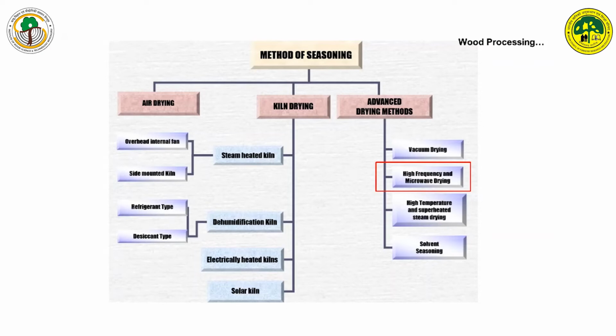If it is a rainy day, the timber may absorb moisture, and if it is a dry day, it may lose moisture. So we don't have any control over the natural environment, so we cannot control the degrade either. Although air drying is economical, I mean, we don't put much energy in terms of monetary value, however, sometimes the degrade can be more, and the drying period is quite lengthy compared to other methods.